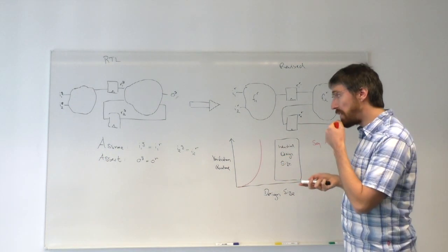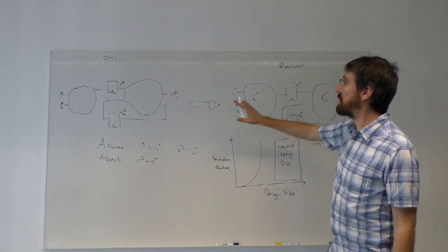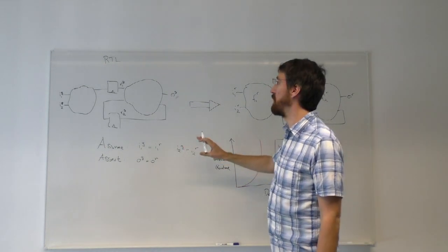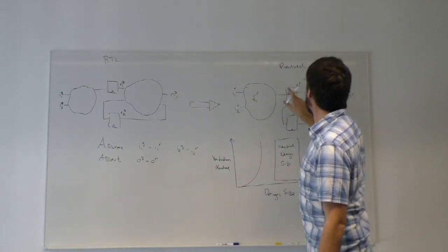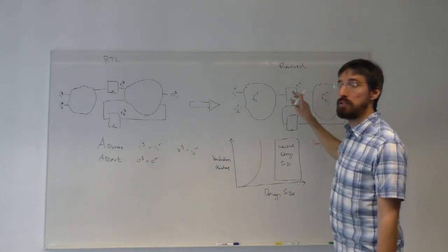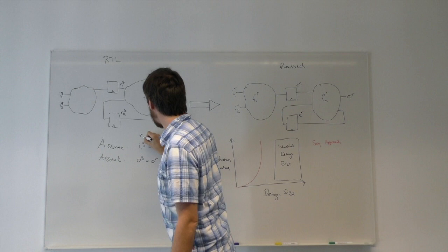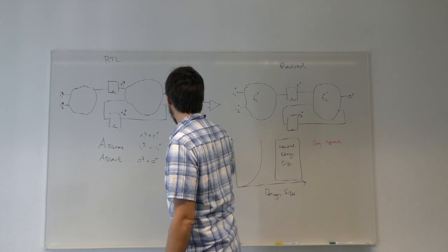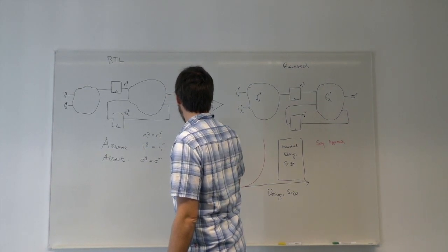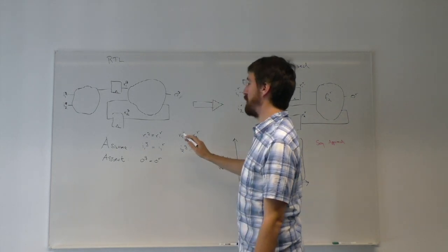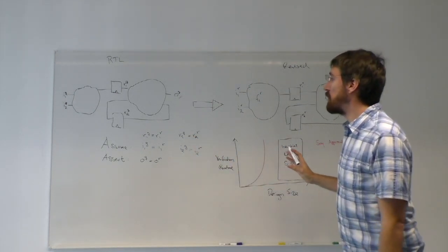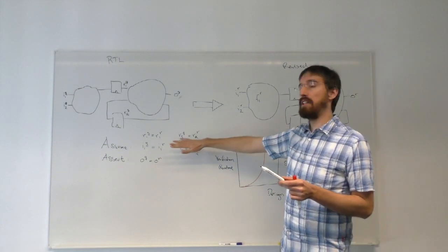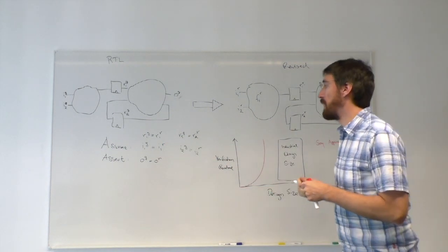So how you can reflect that is you write down exactly how it is in this case. In addition to specifying that the inputs are equal, you could also say, well, the outputs of those flops are probably equal too, so let's assume this. So I would write down that R1G and R1R and R2G and R2R are equivalent. This is an assumption which the prover would use. And then you need to write down an assertion too. Otherwise, it may be an invalid assumption. So you basically need to prove that the assumption is correct.